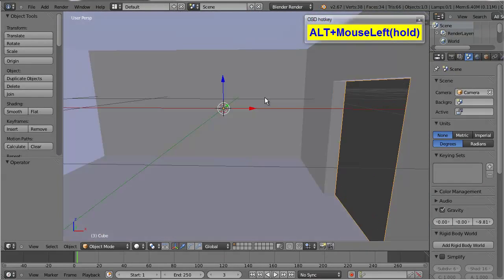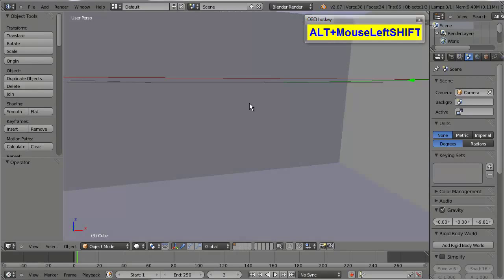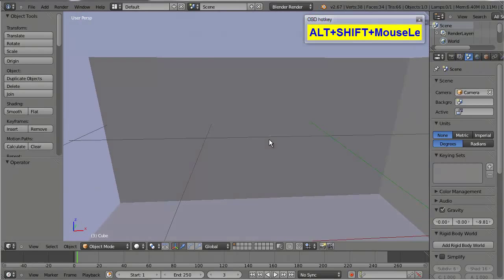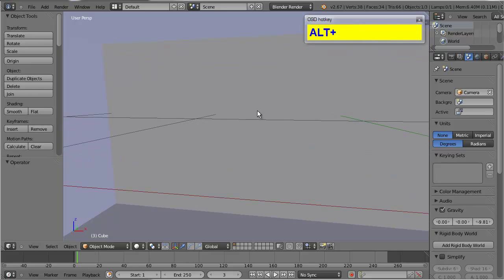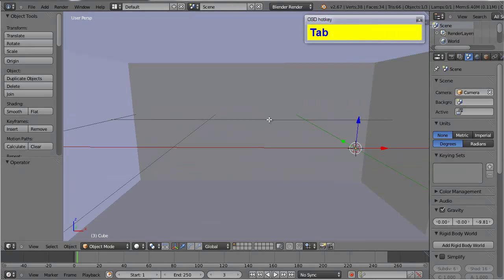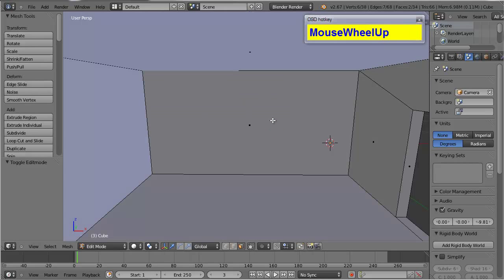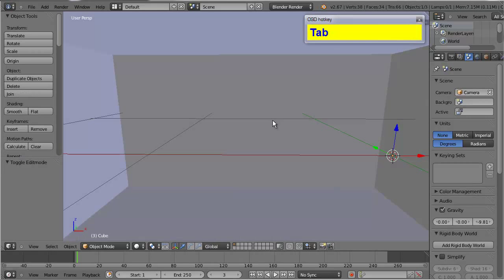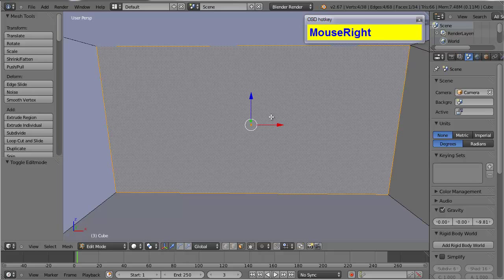And in fact, the best way, the easiest way to put a window in is by extruding the face that you're trying to put the window into. And to do that, I'm going to enter edit mode by pressing the tab key. You can toggle back and forth between object and edit mode. But I'm going to go into edit mode, and I'm going to select the face that I want to put a window in, and I'm going to press E to extrude it.